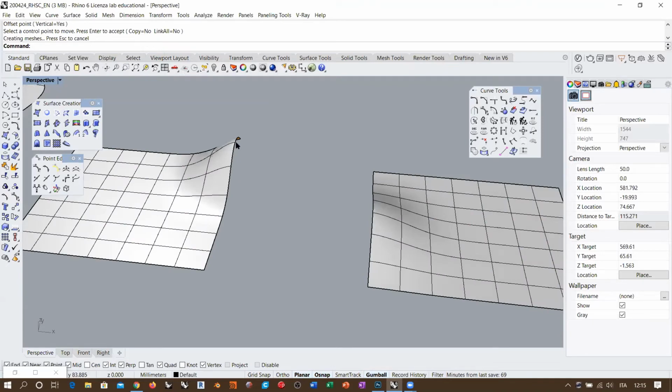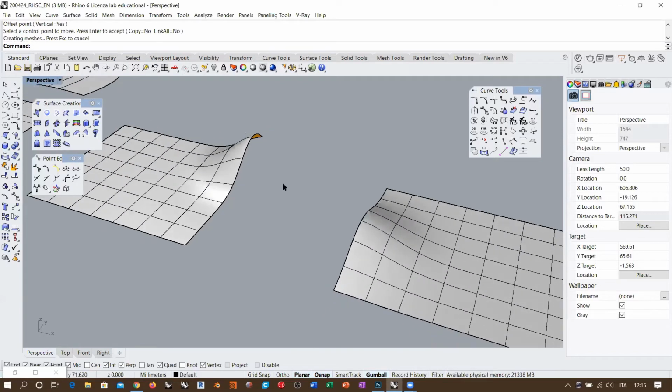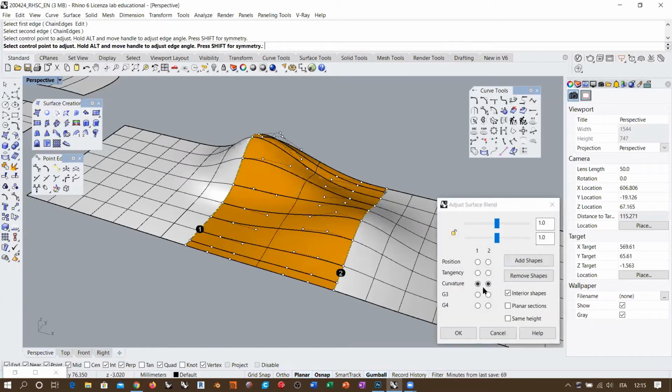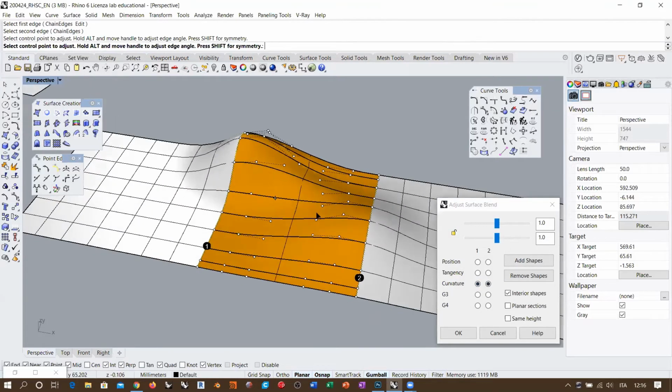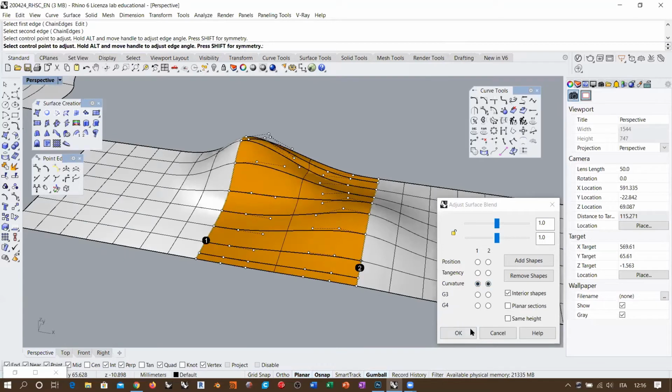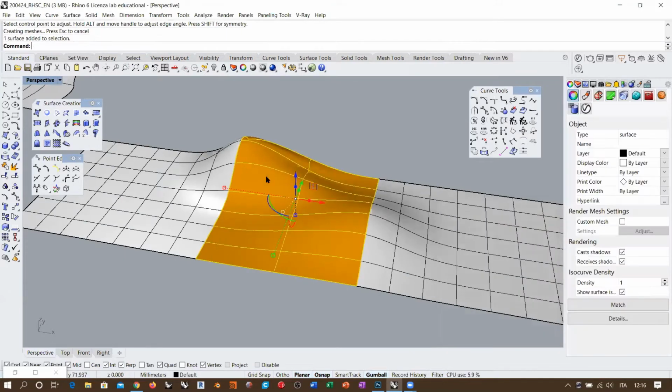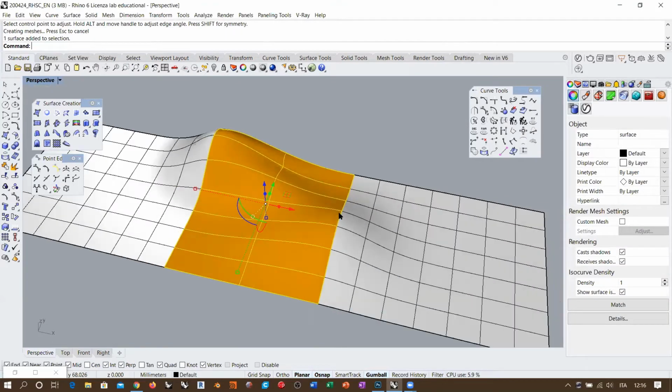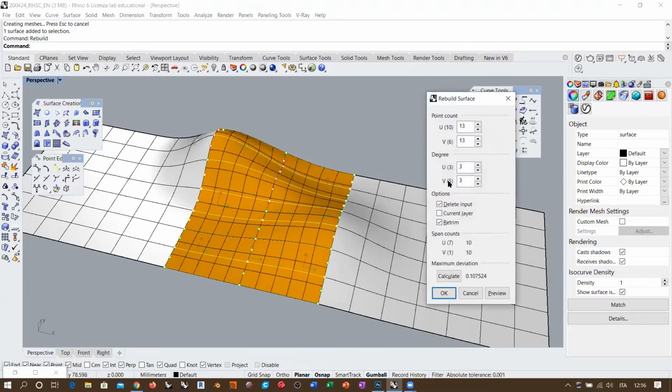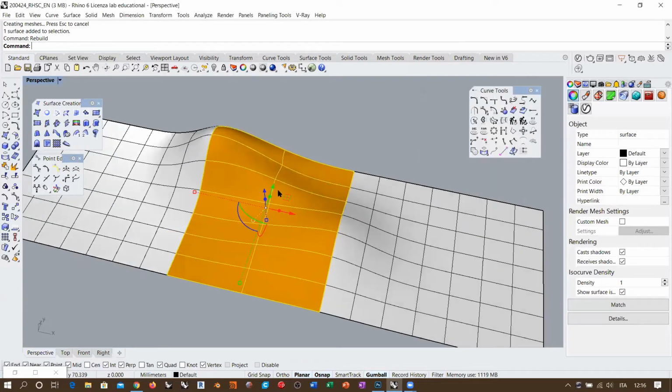smooth connection with curvature continuity between these two things here. Now, of course, the best thing that we can do right now is eventually create a blend surface. So if I blend this with this, I can automatically set the continuity with curvature, right? But the problem is, remember that if you set curvature, you will have a single span cross section coming up from this, so you will have a degree 5 surface in the B direction, okay? And we don't want this, okay?